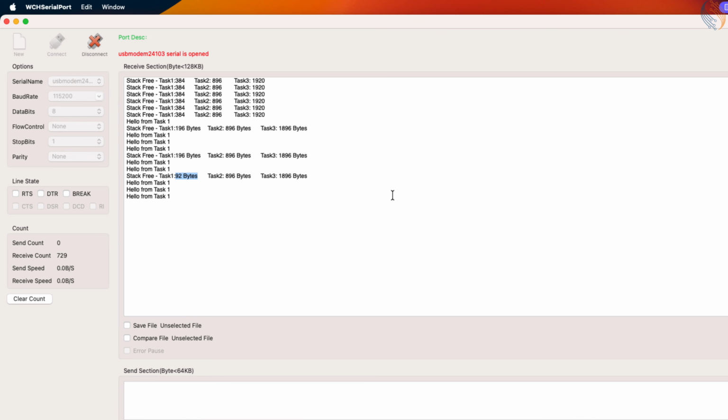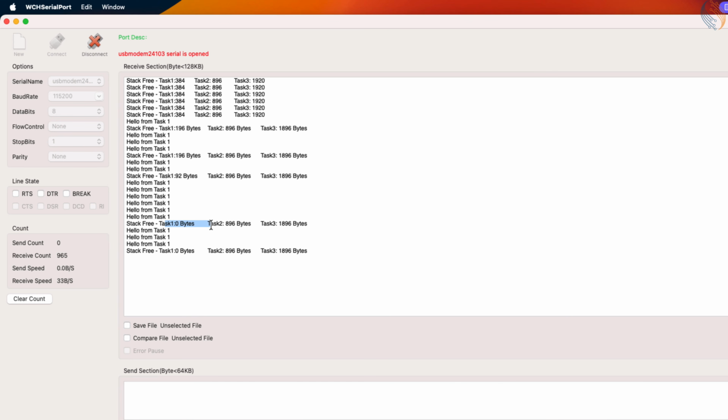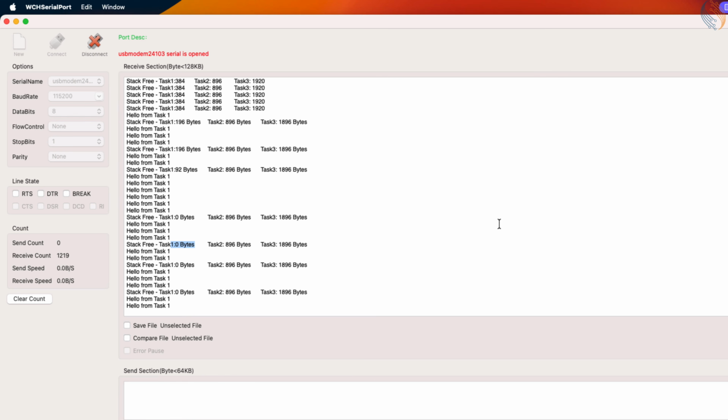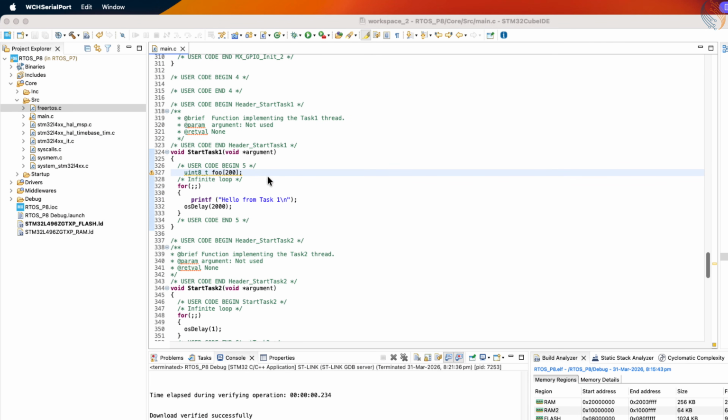You can see that the monitor task is simply printing that the stack space is 0 bytes, which indicates a serious problem. However, notice that the task is still running and continuing to execute its code, and that's happening simply because we're not actively accessing or writing data to that memory location. We only created the array declaration, and without actually performing any read or write operations on that memory area, the rest of the task's code continues to run normally.